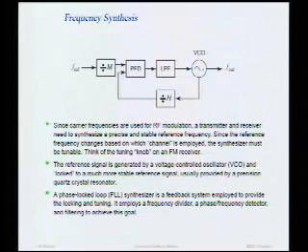Now, why would you want to do that? Synchronization with clocks. Synchronization of the clock from the system and the broadcaster. How does using 10 megahertz, let's say, help you? No, you're right. But the key point is that in order to communicate, we need to agree on our clocks, right? The sender and receiver need to have clocks that are well synchronized. And you're exactly right. One way to do that, a clock and data recovery system, will take the clock of a received signal and regenerate a new clock based on the data. That's more at the baseband.